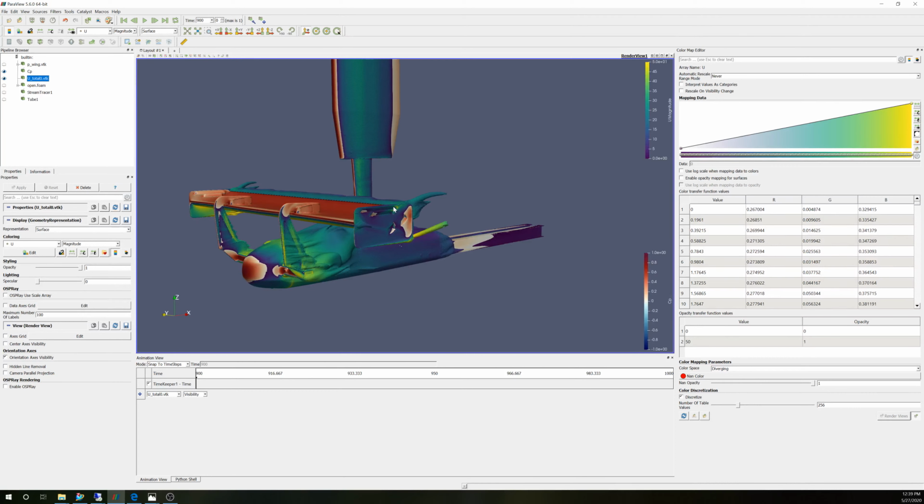You see all these slots in the end plates, and a lot of people don't really fully understand what they do. What slots do is relieve some pressure from the top side of the wing, so you're losing some downforce right there by relieving some of that high pressure. However, you're decreasing the vortice that's caused at the top. So this is the upper vortice, and when you're relieving some of that pressure, you're decreasing that, so you're actually decreasing overall drag. The reason that's beneficial is because most of the downforce produced by the wing is actually on the bottom side.